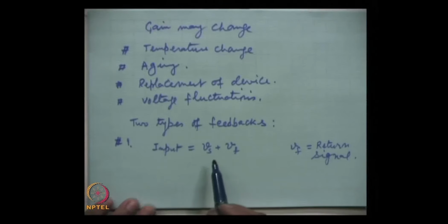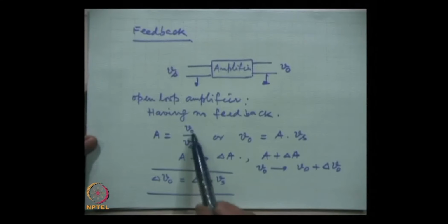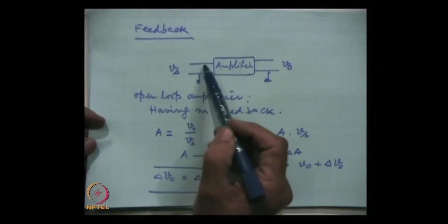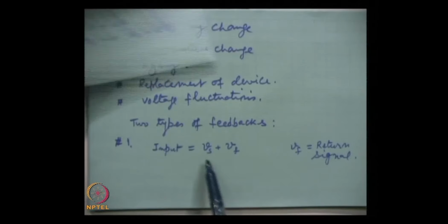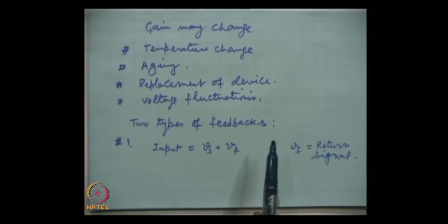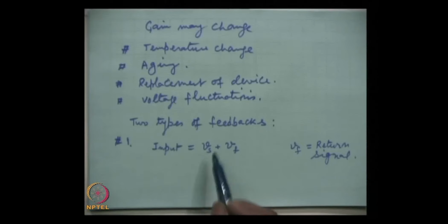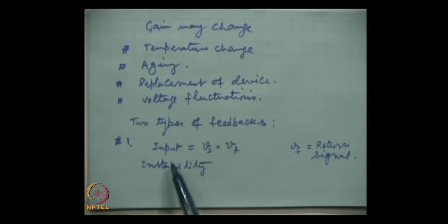In this situation, we can see right from the fundamental equation, that if the signal increases, then the output will increase. So, the output now increases, hence this will give a higher value of output, and again a higher fraction, because the feedback network is constant. For example, if it is 10%, then it will feed 10% of whatever is available at the output. If the output has gone high, the 10% portion which we are feeding also becomes high. So, this will keep on increasing. Finally it will amount to instability. If the output keeps on increasing every time, then this will bring instability to the circuit, and this is known as positive feedback.